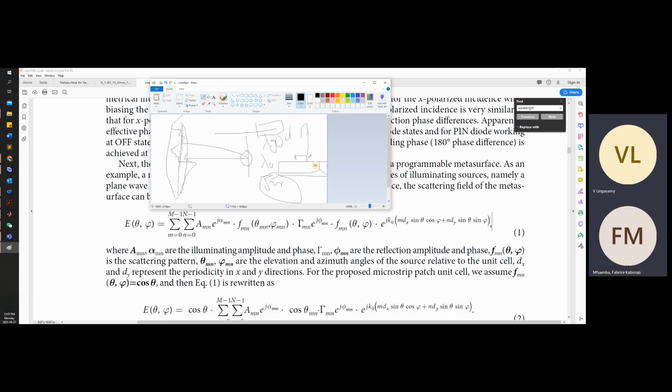Here, what we are doing is printing some patch antenna, which we call an artificial dielectric, or metamaterial. By printing some form of metallic structure, or complementing it, we can control the overall effective dielectric constant of the substrate, or we can say the whole module. That is the fundamental principle for the artificial dielectric, as well as metamaterial.